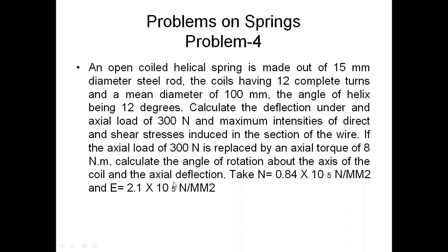In this problem we have calculated T and M. T is the torque and M is the moment we have calculated, based on the load acting on the spring, which is 300 Newton. If you see this problem carefully, if the axial load of 300 Newton is replaced by an axial torque of 8 Newton into meter.